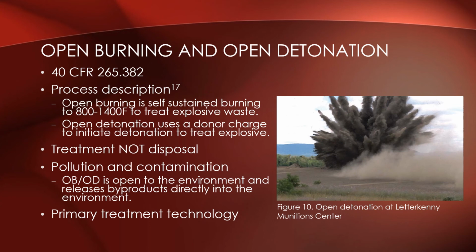Open detonation physically changes the chemical makeup of the waste as the explosion passes through the material faster than the speed of sound. Open detonation involves the placement of explosive waste into the subsurface and utilizes placement of a donor charge into the subsurface with the waste explosive to initiate detonation and destroy both the donor charge and the explosive waste.